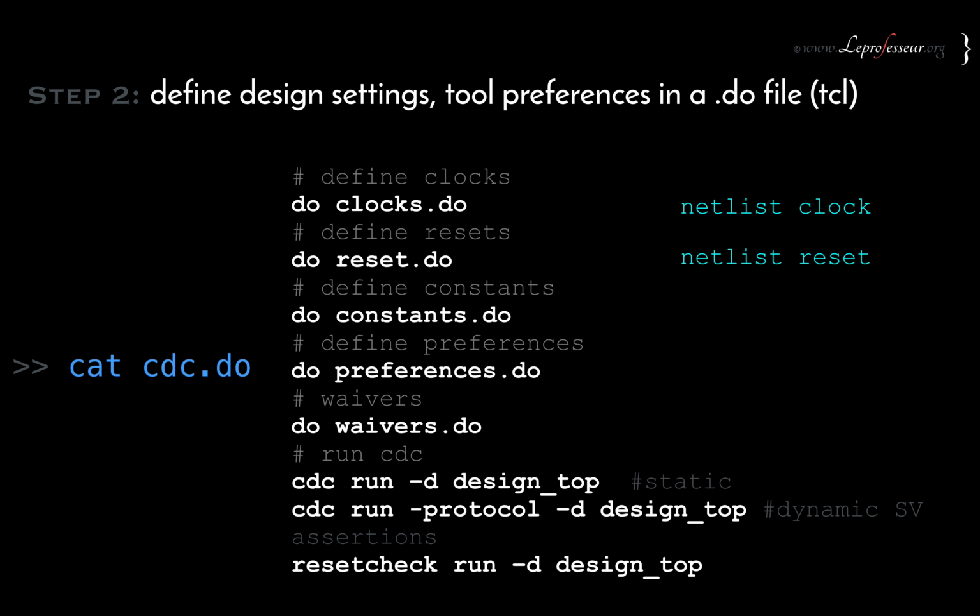You can define the resets the same way. What are the different resets in your design? The tool can automatically infer the clocks and resets. If the tool infers clocks and resets automatically, you have to review them and then say, okay, these are good to go. Nevertheless, it is important to understand that all the clocks should be defined by the user with the proper clock period. Then the tool will give you better results.